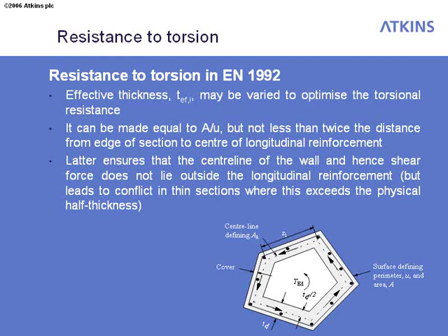And the way the model is going to work is we're going to design basically each strip as we do for shear, as a beam for shear, so using the truss model. And basically if your truss is lying outside the reinforcement, well, it ain't going to work because the cover will just come off. So that's an overarching requirement, that you mustn't have an effective thickness that's smaller than that.